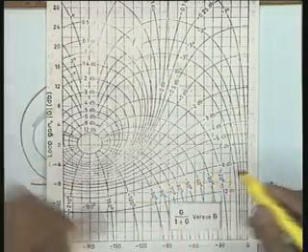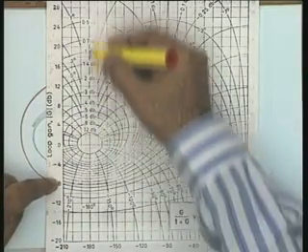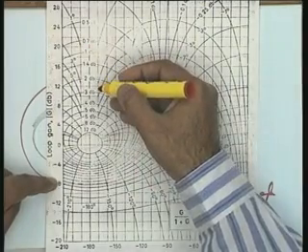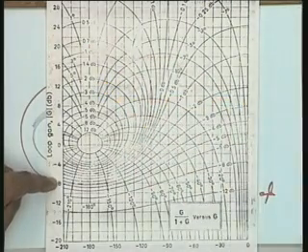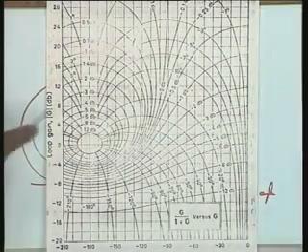Look at this, that M is equal to 1.2, 1.1 which I am saying, here the calibration is in terms of dB. So, 1.2 means the corresponding value is written here, 20 log 1.2, that is all. The calibration on the Nichols chart has been given in decibels, it does not matter.